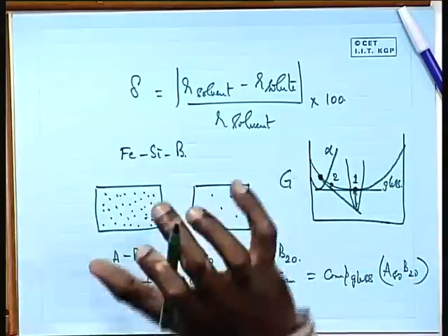If you add this, that should give you the total number of B atoms which are there from the starting glass. Otherwise, you are creating some atoms, and you cannot create them. The law of conservation of mass has to be maintained, the first law of thermodynamics has to be maintained. So if you do it that way, you will always get a mixture of amorphous phase plus intermetallic compound. This is what is called primary crystallization, not a polymorphous crystallization.